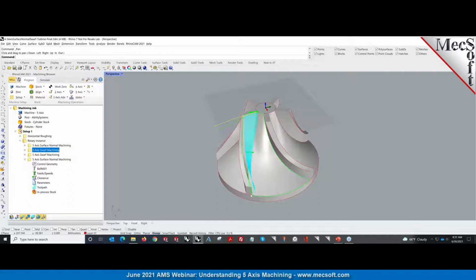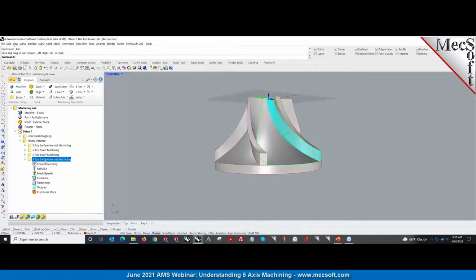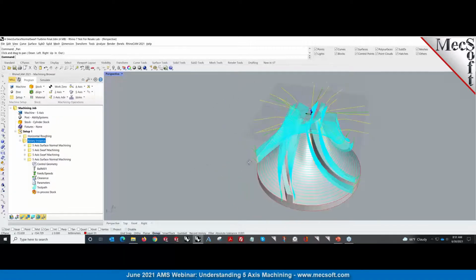As you can see, there's a twisted wall, and the cutter cuts using the side of the cutter and checks to the bottom surface. Same thing on the other side. And then finally the top here. And then very similar, we did a rotary instancing to get the entire set.